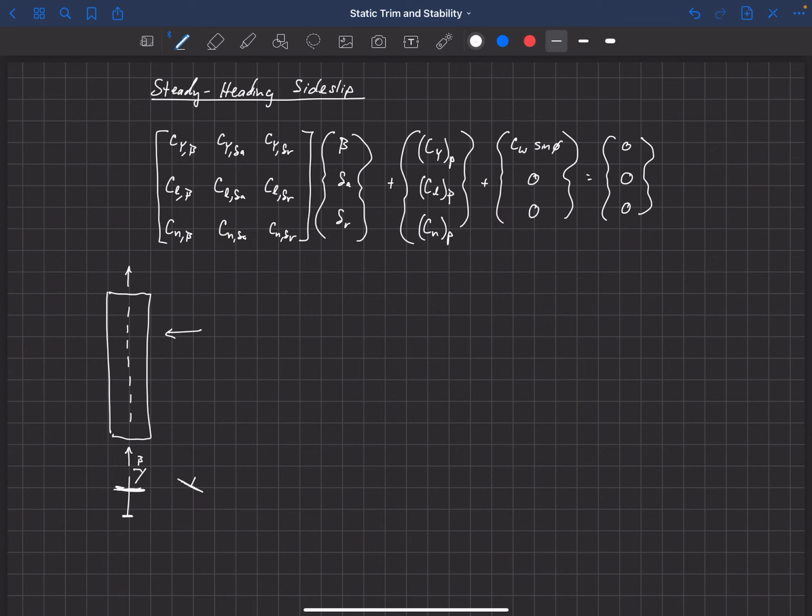So he's going to have to bank the aircraft phi and have some non-zero bank angle in order to keep the aircraft oriented and moving in this direction here. Well, that becomes a little problematic because the wingspan of aircraft is usually rather large, and so just a very small bank angle will cause a tip strike during landing. So although this is an option for trimming the aircraft out so that he can keep the aircraft aligned with the runway, this is not very conducive to takeoff and landing because of a tip strike scenario here.